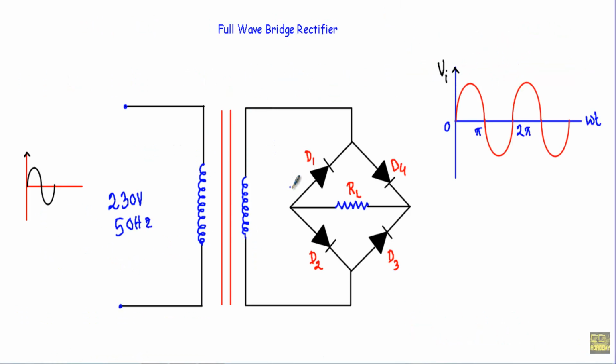If you look at the structure of a full wave rectifier circuit, you will see the secondary winding has a resistance of R2. The diodes has forward resistance or dynamic resistance or AC resistance RF, and the load resistor RL. Therefore, I will get our PIAC equal to IRMS square into R2 secondary winding resistance plus dynamic resistance of the diode plus the load resistor RL.